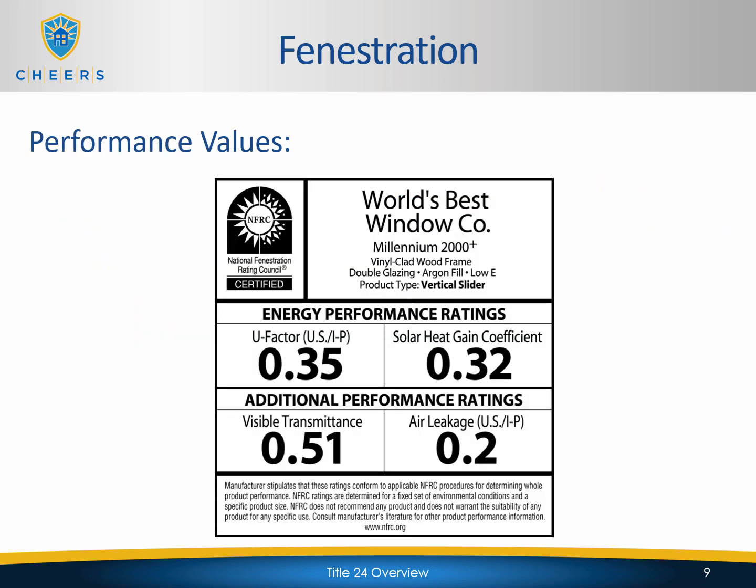And this is an example of what the temporary label looks like. And those are the values associated with these labels. Now, one thing I want to point out is that as a HERS rater, you are not required to verify window values unless you're specifically contracted to do so by the builder or maybe the installer, or maybe you're taking part of some kind of above code program that requires you to do this. But window values are not, I repeat, they are not a HERS measure. But nonetheless, they are a Title 24 requirement.